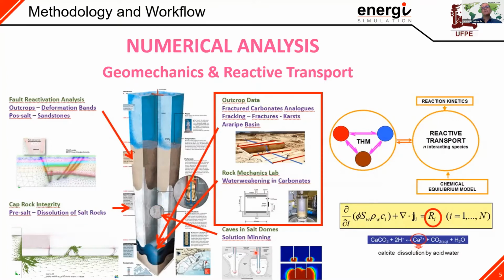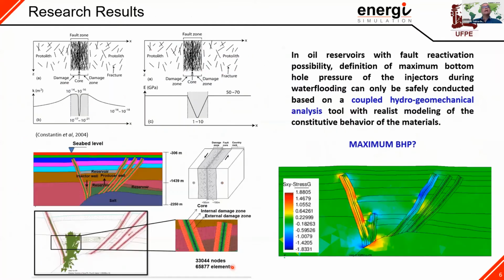So the idea is to store fluids, and what we are doing is for non-conventional conditions, conditions that are not covered by commercial software because of the depth, the water rate, the temperature. We are working on the build of this cavern and the stability and the operational conditions of these caverns. Regarding fault reactivation, we believe that it's a complex problem, but we believe that in an oil reservoir with fault reactivation possibility, the definition of maximum bottom hole pressure of the injectors can only be conducted based on a coupled hydromechanical analysis, considering the complexity of the material.